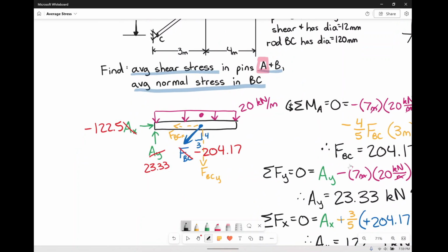So at A, we had a box, right? Here's our beam, blown up nice and big. It's technically going out and it's technically going up. So in total, it's going to look like it's holding this direction. It's pulling that direction, that is the reaction at A. It should actually be the other direction, it should be going up. It's that way. So there's the reaction at A. It's holding it up and over, keeping it from flying away on us.